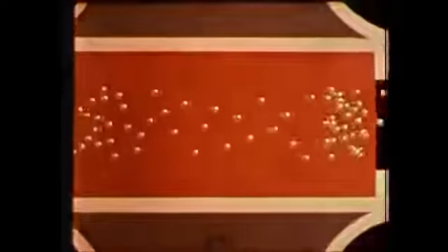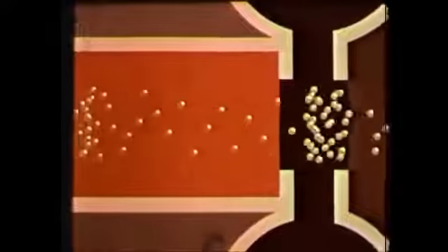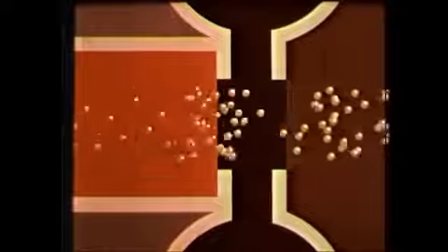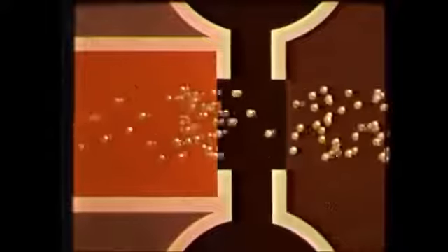In this space, known as the drift space, the fast electrons will overtake the slow ones and bunches will be formed. The second resonator is located in the position where the bunches contain the greatest number of electrons. The bunches arrive at the second resonator at intervals corresponding to the frequency with which the first resonator oscillates. As both cavities are made identical, these intervals also correspond to a resonant frequency of the second cavity.